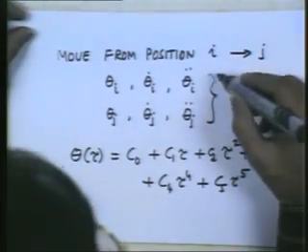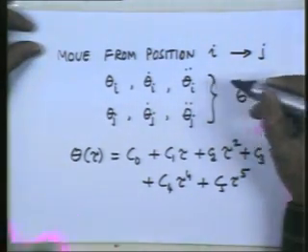But acceleration specification will require, again, as we mentioned, the idea of a user interface: the user has to give you more data, more requirements, more specifications. So it is not necessary that we use a higher degree polynomial only when there are acceleration specifications. Even otherwise we may use a higher degree polynomial. So I will now highlight one such case where we would like to use a higher degree polynomial in terms of trajectory planning for an individual joint.